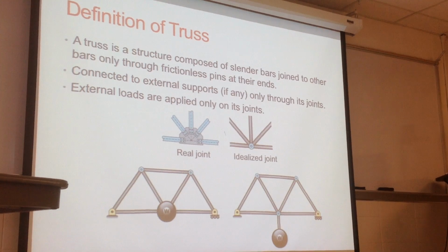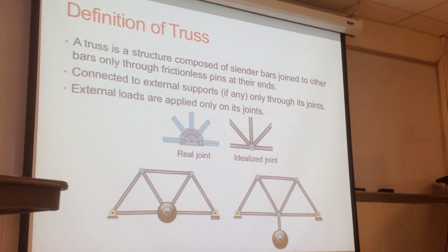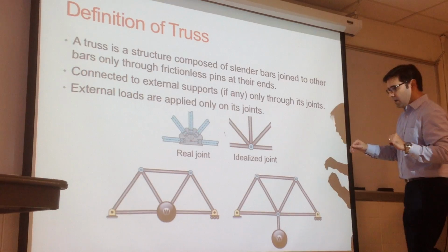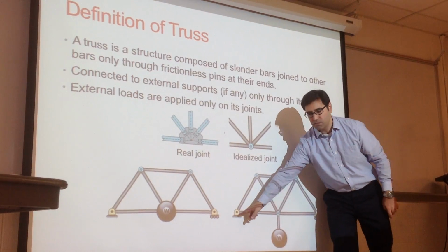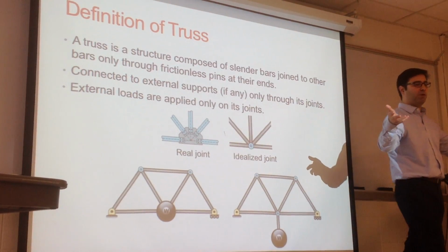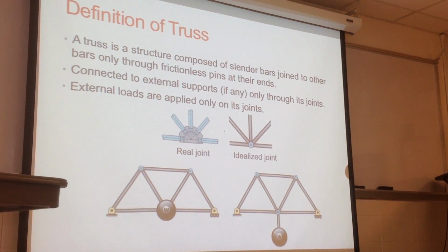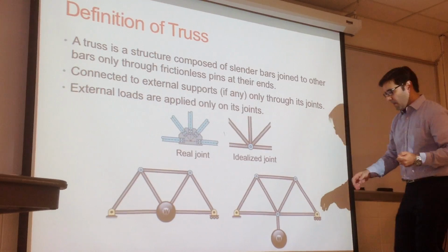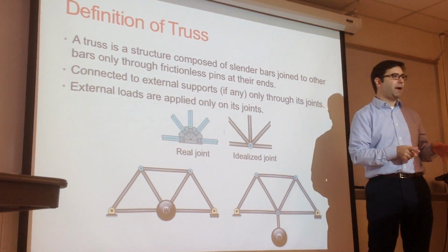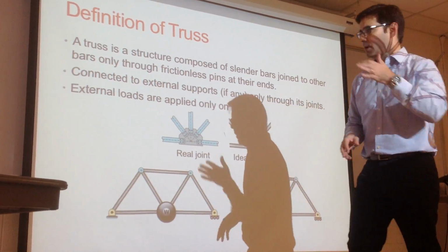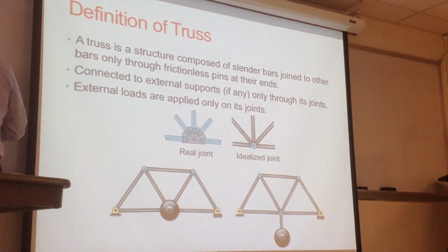But the other thing that is important for trusses is that the support, which could be the support for a bridge, but could also be the support of a wing into the main structure of the fuselage, either the supports and the loads have to be applied at those pins. Alright? So basically, let's say this is a wing spar.